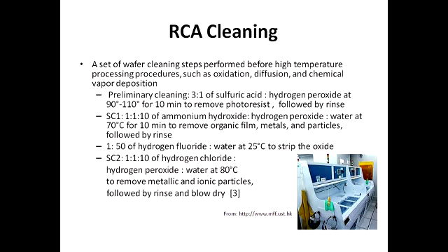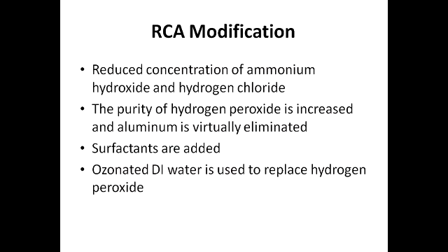Then the last step is SC2. It's to remove ionic contaminants using hydrogen chloride, and every step is followed by rinsing. In the last step, the wafer is blow dried.